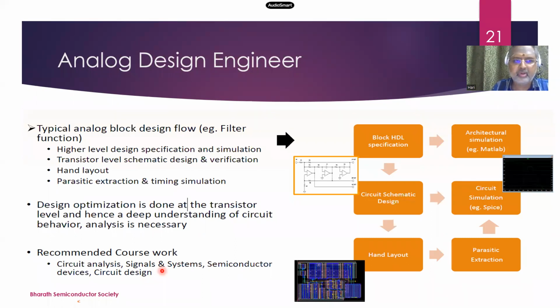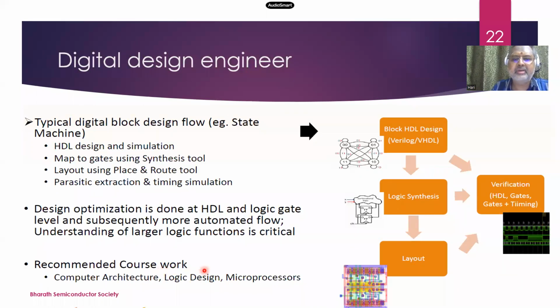That's the expectation. Digital design engineer is another thing. Basically, you have to write a block level HDL design in Verilog based on the specification. Then you do logic synthesis. In parallel, you verify using SystemVerilog or UVM, those kinds of technologies. Then you do a layout, then the back end of the design, and you extract the timing, go back to verification, do a bunch of static verification, then you send it out to fabrication in GDS2 format. We'll talk about manufacturing in a moment.